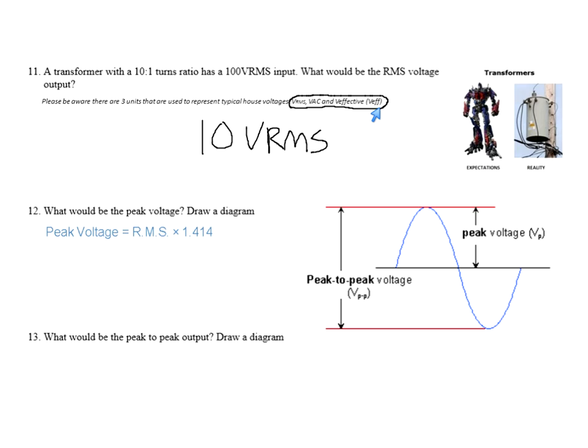They'll mix them and match them with you. They might say there's 10 volts AC coming into that transformer. What is the RMS on the secondary? Okay, so what if the output is 10 volts RMS? How would I find the peak voltage? Every exam that you take to get an interview, if they give you one, will have an RMS conversion on it, so you need to know this.